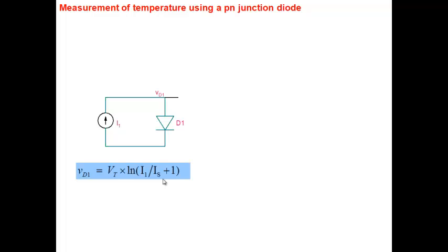Calibration. So what you're saying is, if I measure the diode drop, if I'm using it as a temperature sensor, if I'm measuring the voltage here, how do I infer the temperature? All right, how will you do that? The difference between two temperatures will become dependent upon where we are measuring it. It's not linear, so it would be difficult to calibrate it.